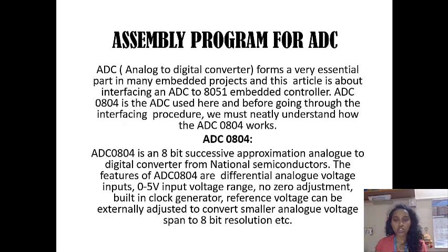There are also two very important, crucial factors when considering an ADC. One is the conversion time and the other is resolution. Resolution can be 16, 8, or 32 bits, but the higher the resolution, the smaller the step size, which is very important. And conversion time is the time required to convert analog to digital data, and that is also a very crucial factor when considering an ADC.